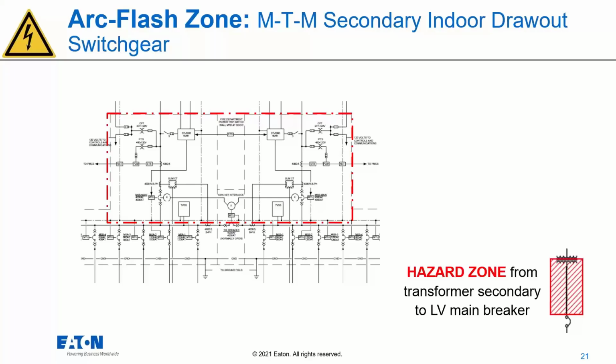And if we have something like a pole-mounted fuse or pole-mounted vacuum recloser, it needs to be able to ride through that large amount of current that is initially pulled in without tripping in order to really energize the unit. So then it can be on after it rides through that. So the settings have to be loose enough to allow that current to rush in. And you can't have that tight protection in that scheme to give us a quick trip or fast clearing time and low energy. All right, so looking at the situation with no relay and no secondary CTs, just that primary upstream vacuum recloser.